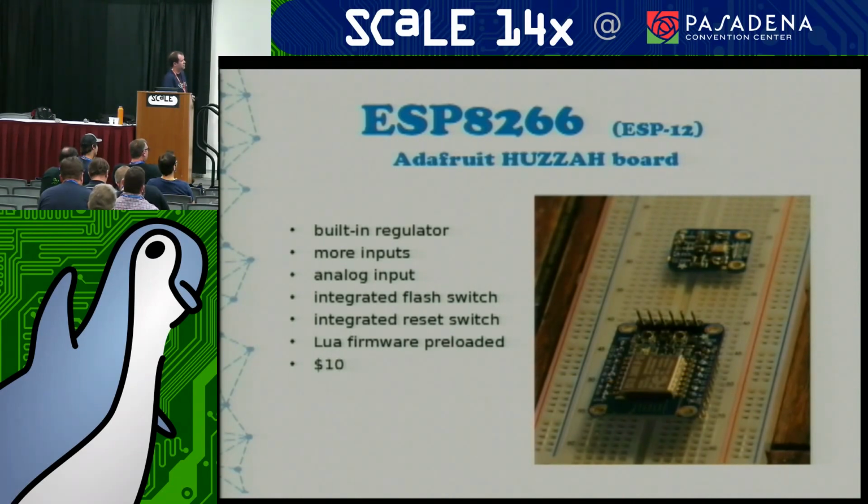That's life. So I've been aware of this one, but I found, I guess, the 12th generation, but they don't do an incremental thing. But anyways, Adafruit, which is a popular Arduino retailer, they sell a board that's based on the ESP12 model of this chip. And it has the voltage regulator and the programming reset buttons, and a whole load of inputs and outputs on the side available. It's got pins for connecting USB. It's like pretty much all in one. So that plus the BMP180 temperature and pressure sensor, it's a lot simpler than multiple physical components. And I found that these are incredibly reliable.